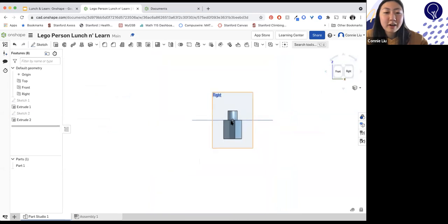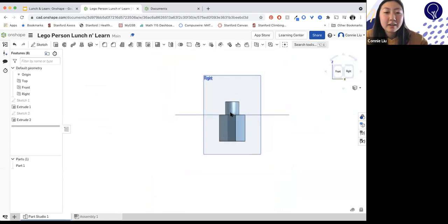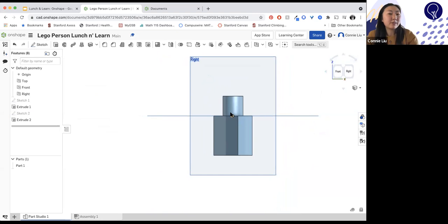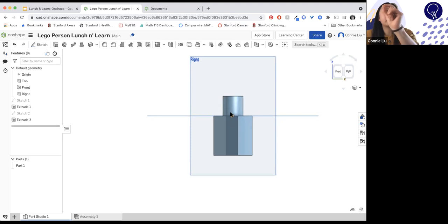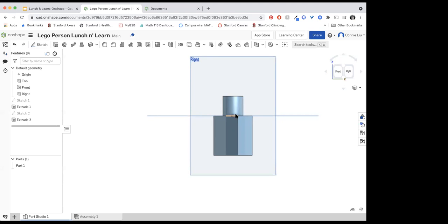Any questions so far about making a body, about extruding a rectangle versus a circle, and how you do different planes? How do you align 2 points again? I just dragged the point that I created in the middle to the other point. And then it locks in when it's in line with each other. Oh. Mine's not.